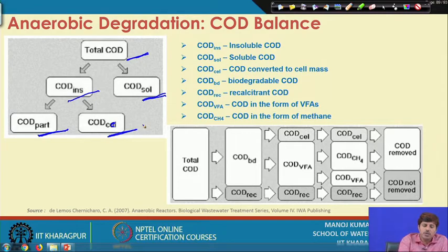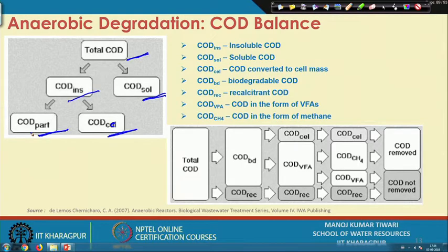So, this insoluble COD, because the particulate matter is in the suspended or particulate phase, cannot get dissolved in the water, that is one aspect. The cellular mass, COD which is converted to cell mass, is also not dissolved in the water. So, there will be a constituent of the COD in the form of COD cell as well.